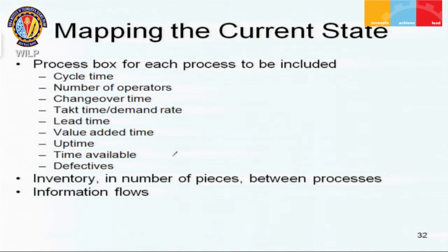It is not necessary to go about calculating averages and doing any kind of sophisticated math, because the purpose behind the value stream map is not to have very detailed and precise numerical information. We are looking for orders of magnitude of data with regard to inventory, because we are trying to highlight areas where inventory is accumulating.